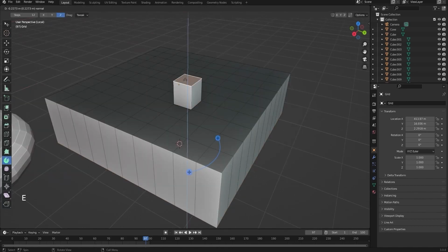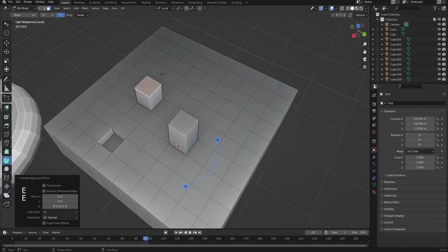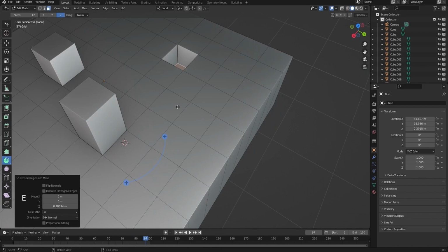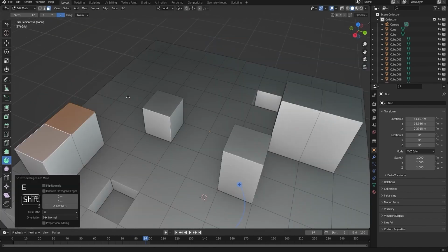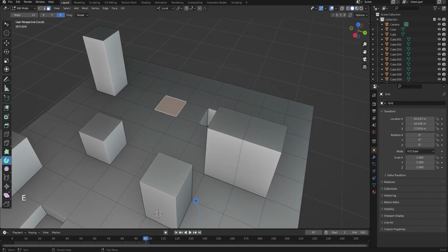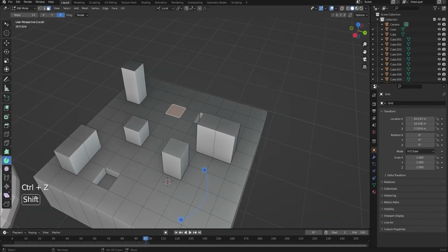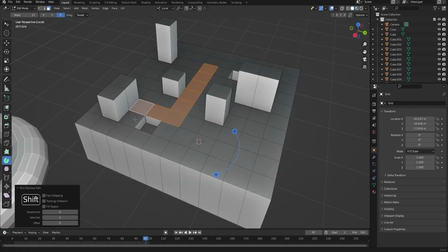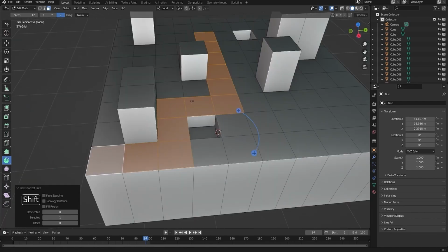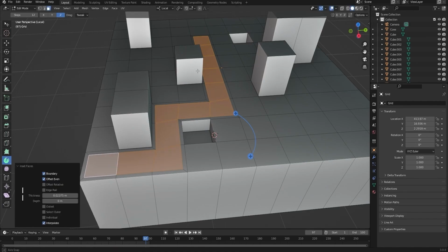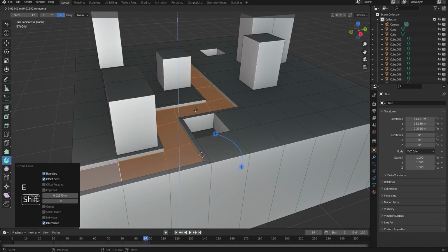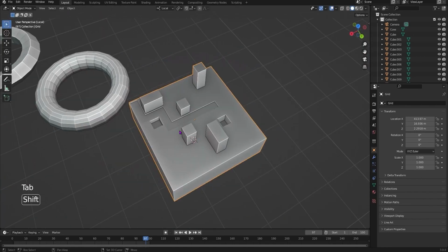When using the grid tool, this can be a very useful way to create things like cityscapes, in which we can extrude a lot of small squares up and around. We can also make indents in the grid so that we can mimic things like sidewalks and gutters. So there are two ways to inset things in Blender, and that's to inset individuals, where each of the individual faces that you have selected inset inside of themselves, whereas you can use something like path selection, and then you can use continuous inset to make it so that you have one full shape.